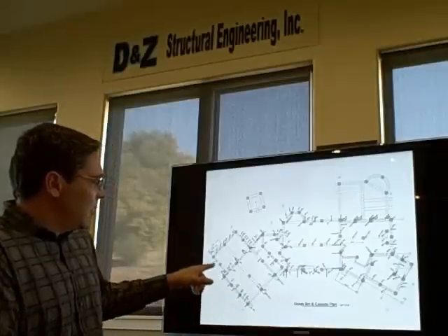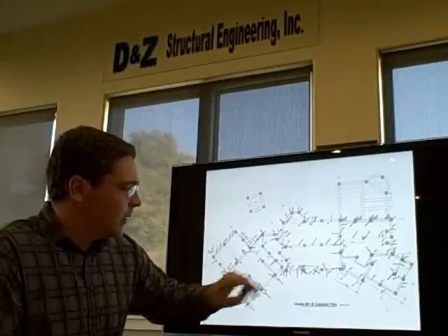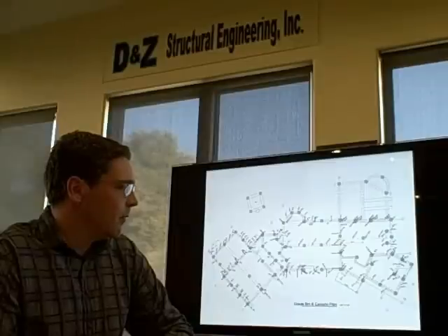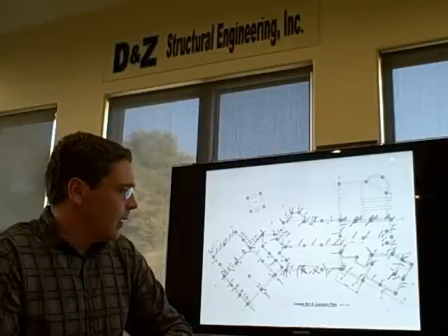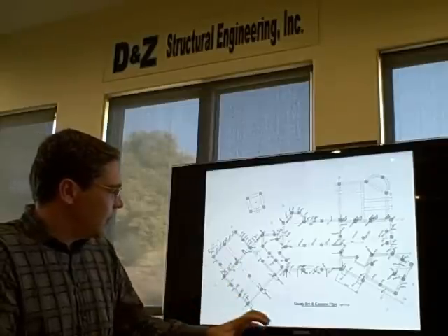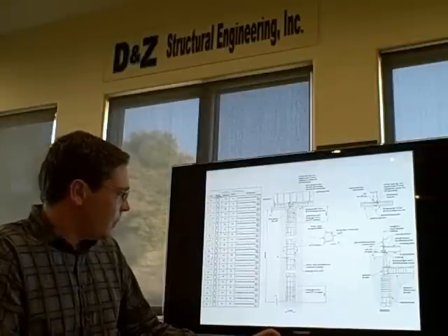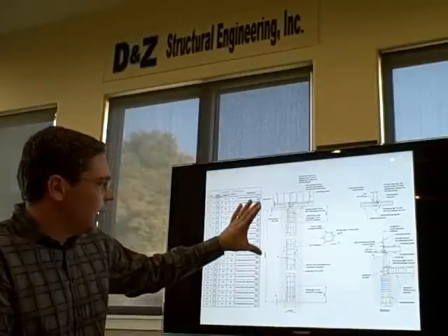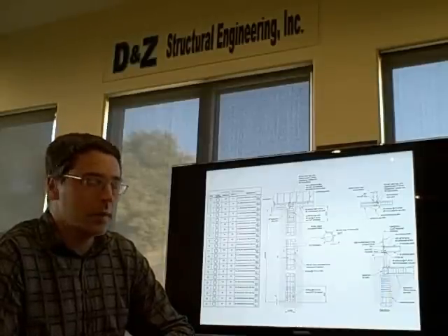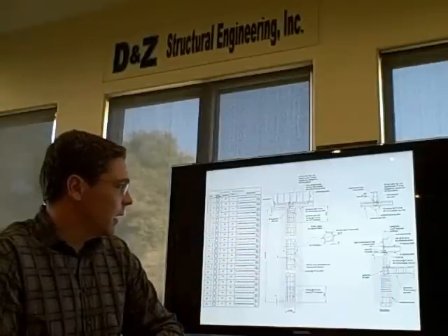Typically speaking, caissons are laid out in an economical fashion to utilize the concrete grade beam design parameters, get the most out of its strength and greatest span that we can. The load to the caissons is dependent on the load coming off of the grade beams, and that load is transferred into a depth. A certain depth is required to resist a certain load, and it's done by skin friction, the soil resisting alongside the caissons.